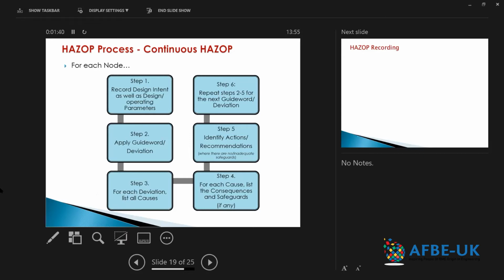And when you've listed the consequences for that, you would evaluate those consequences. That's where the team starts to talk about what could happen. And that's where the safety engineer, for example, contributes as to what the ultimate, unmitigated consequences are, because that's what you're looking for. You're not just looking for a consequence that says there's a high temperature, the pipe work is going to be heated up above design temperature. So what then happens after that?